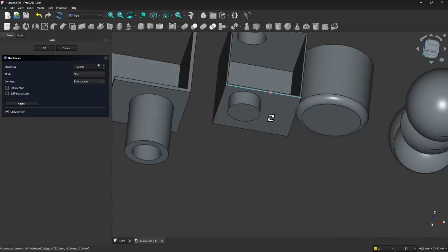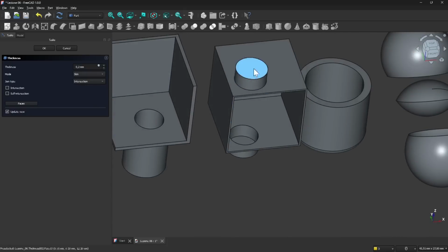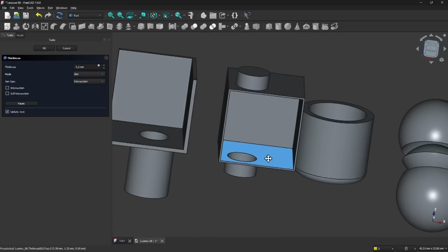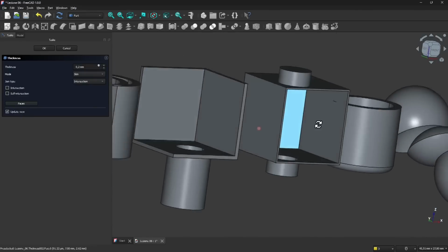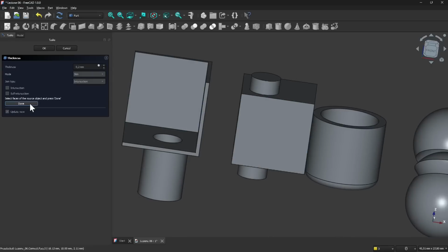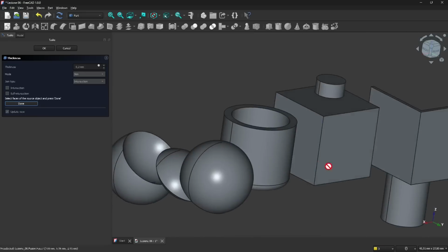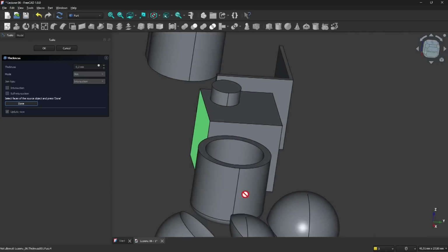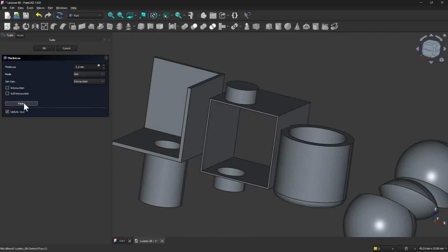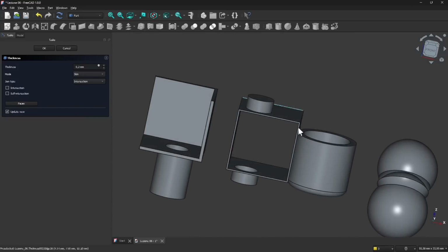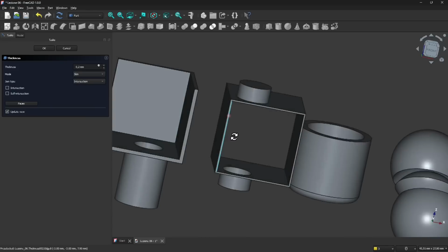And we can see how it behaves also with the other united element. Now, if we want to subtract more faces from this, we want to delete more faces, we can use faces, select this other one again, and then let's select also the back. Hold Control to select both with the Control key, and then done. You can see now we have removed also the other face, leaving the rest intact.